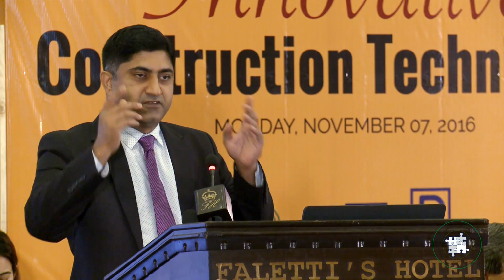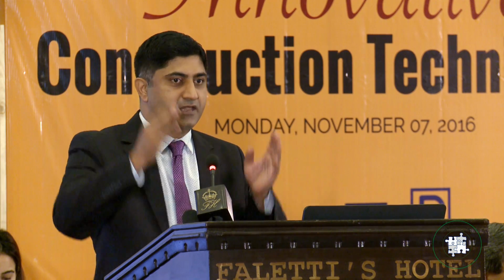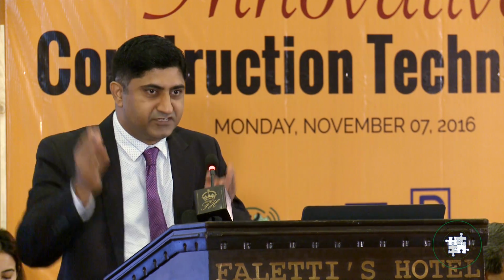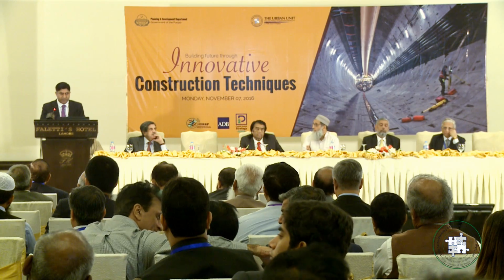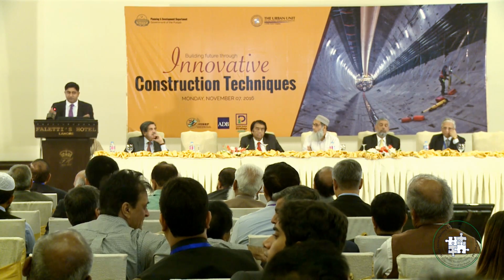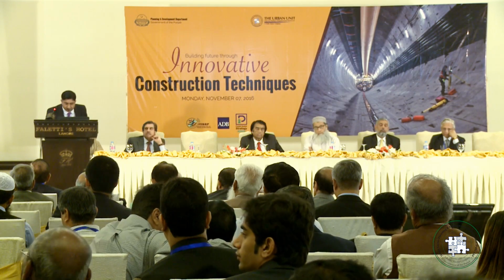The difference is that any reinforcement that needs to perform in a pavement layer needs to go through a tension membrane effect. It needs to undergo deformation to pick up the load. If it doesn't go through deformation, it doesn't pick up the load, which means it is not performing. So that's the key difference between the two mechanisms.